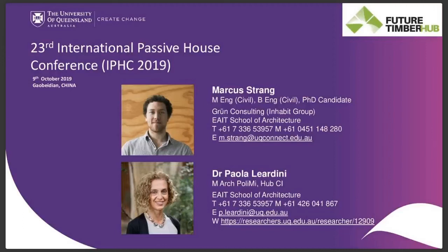So it can differ, and it's always worth doing a hydrothermal simulation to look at that on a project-specific basis. From some of the simulations that I did, it looks like you want to have a higher resistive vapor membrane on the exterior with the insulation on the interior. However, again, it's worth looking at that on a project by project basis at the moment.